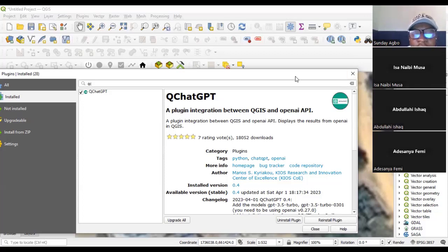So in AutoCAD, you know how to load points and input coordinates, right? Like using align. Remember align in AutoCAD, where you align? Yes. So use align. Pick a physical coordinate of your drawing on the ground, and then use align. Even if it is one point, use it to align so that when you bring it to QGIS, it will fall, even though not exact, at least at the same location where you can then use your move tools to move it.